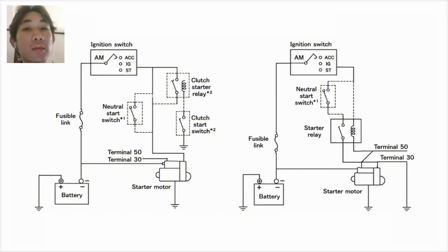It is crucial to know the importance of the starter relay, because the starter relay helps reduce the amount of current passing through the ignition switch. Therefore, this provides several advantages: it reduces voltage drop, gives longer ignition switch life, improved reliability, and better starting performance.